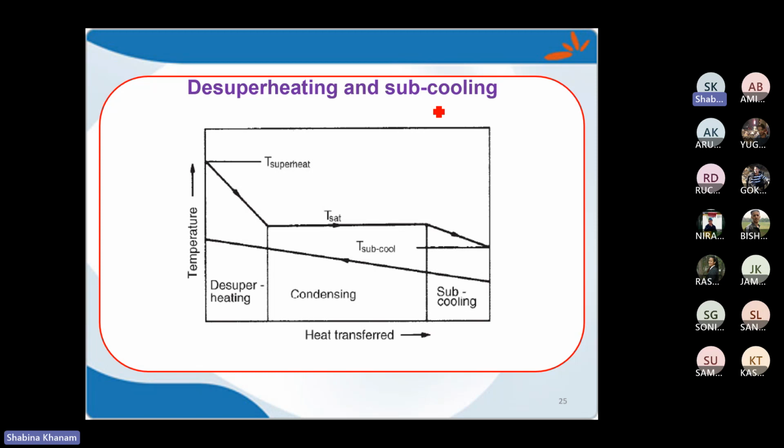So in that case, it is very much possible that if you allow saturated steam to exit the boiler, it will reach the exchanger after some condensation. Therefore, to avoid that, we need to prepare the steam at a slightly superheated condition, so that after heat loss through the pipe, it will reach the saturated condition.